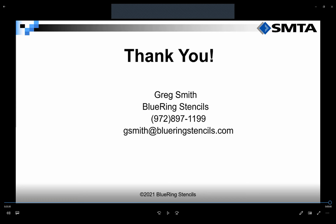Yes. So again, when I hear the word tombstone from a customer, the first thing I think of is excess volume. So typically when tombstoning is occurring, the challenge is, can we take away some volume to solve that issue? And when we take away volume for a tombstone challenge, we would rather take it away from the outside of the pads, like I showed earlier, versus the inside.